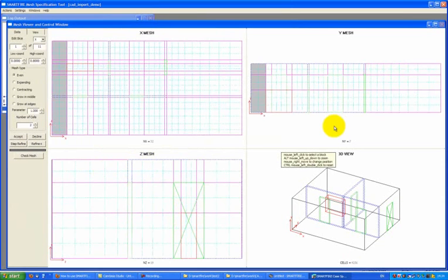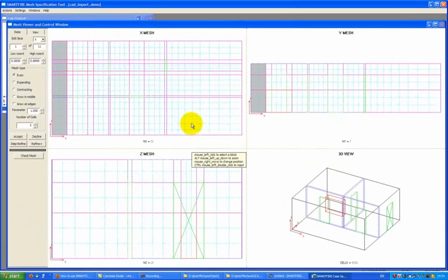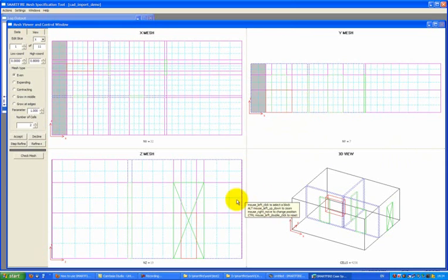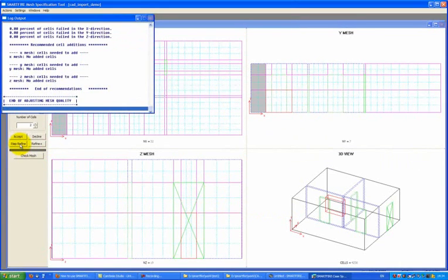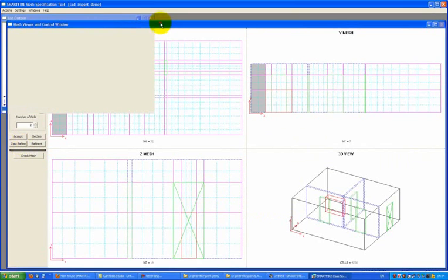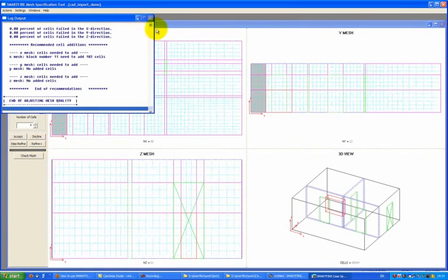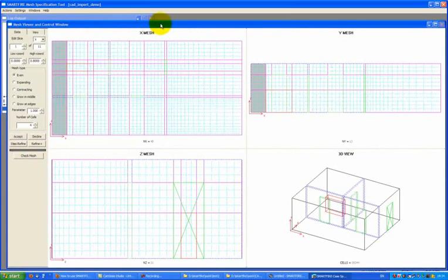And this is the base mesh that we arrive at. As always, it's worthwhile considering the nature of the mesh that's been created. In this case, it's still quite a coarse mesh. It's a coarse, fairly good quality mesh because all the cells are reasonably square and there are no very long thin cells. But actually it's quite a small cell budget and there are quite large cells. So in this case I'm going to perform a step refine in order to improve the mesh and add additional cells.